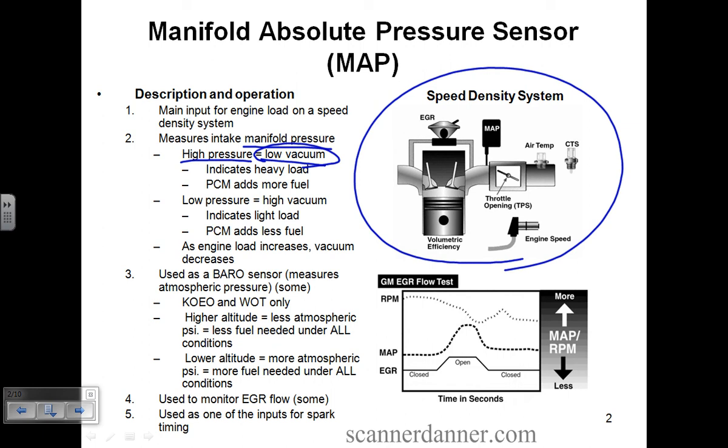Okay, outside of problems, good point, Robert. Outside of problems, when would our vacuum normally be low in an intake manifold? Opposite of idle. Idle is when we have high vacuum. Throttle plate's closed, pistons are moving, we're trying to draw air in, it's being restricted. We create a vacuum from that closed throttle plate. So wide open throttle. Very good.